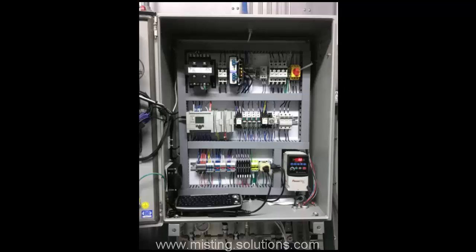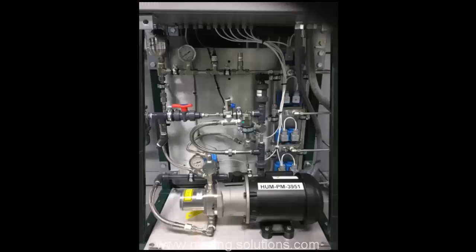Now, I talked about this zone control in some detail in some other movies, but I'm going to go through it here very quickly. Each zone has a different number of nozzles. Therefore, each zone has a different capacity. So, zone 1, 10%, zone 2, 20%, zone 3, 30%, zone 4, 40% of capacity. Zone 4 and 1 together, 50%, zone 4 and 2, 60%, 4 and 3, 70%, 4, 3 and 1, 80%, zone 4, 3 and 2, 90%, zone 4, 3, 2, 1, 100%.